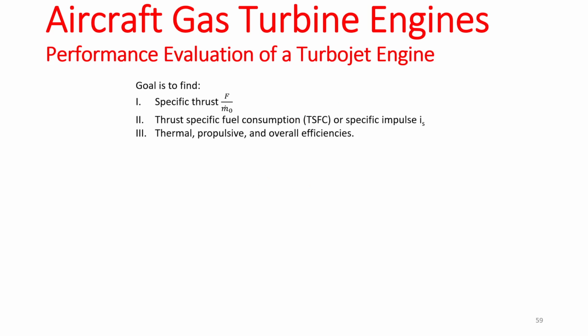But how should we solve the problems? What are the different steps? Or what is the final goal you want to do? What is the final thing you want to calculate? There are essentially three main things that you want to calculate when analyzing a jet engine in general. You want to find the specific thrust, which is F divided by m dot naught. You want to find the thrust specific fuel consumption or the specific impulse. And you want to calculate all the efficiencies: thermal, propulsive, and overall efficiency.